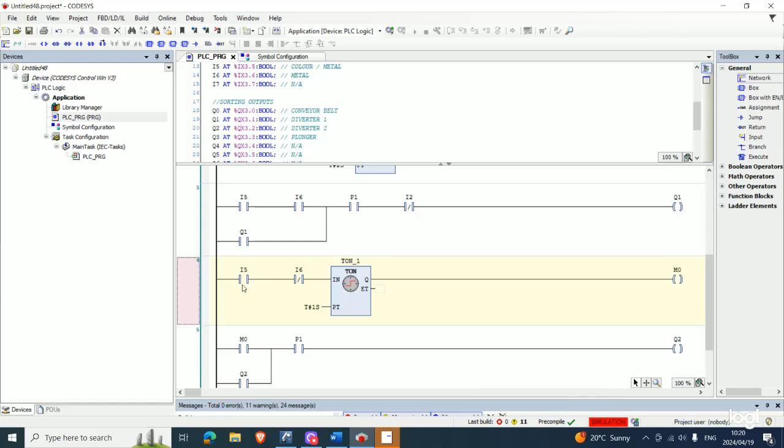So now this new condition is saying only I5 is activated and not I6, right? As you can see, it's a direct opposite of the one above. It's saying only when I5 is activated and not I6. It will evaluate our code by verifying that I5 is correct, then it looks for whether I6 is on or not. If I6 is on, it signals that only diversion should be activated, right?